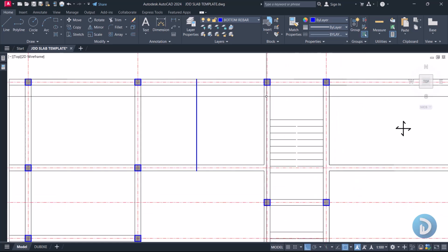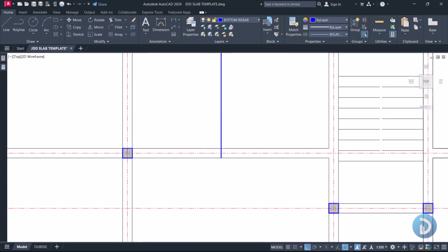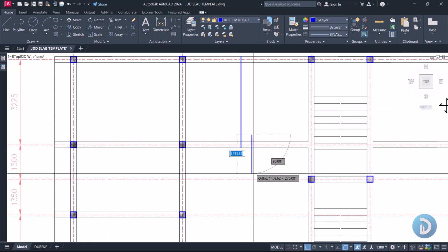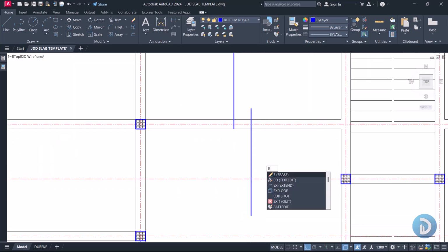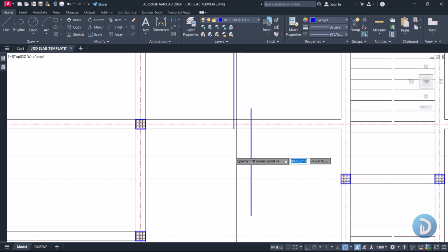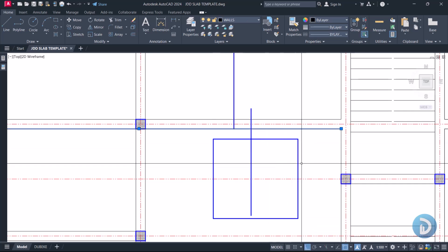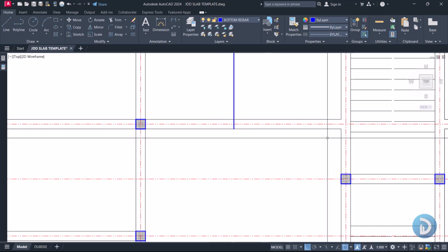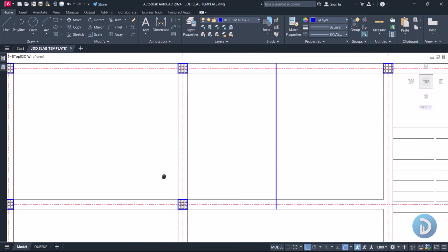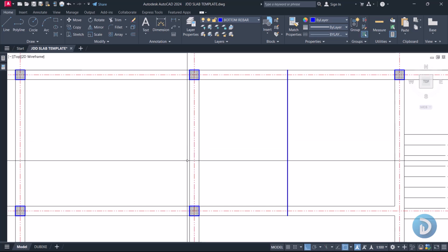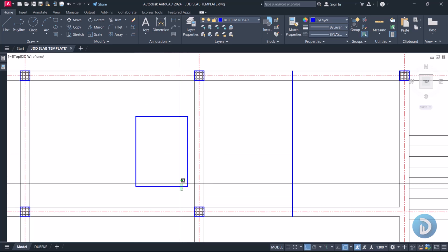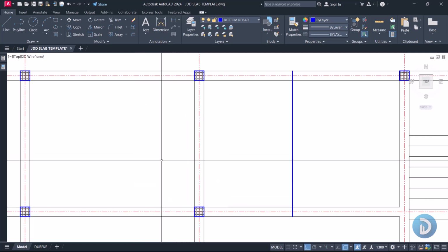All right, then if you still go in the clockwise direction, if you look at this part, you will agree with me that we have a slab just beyond this beam. Okay, we still have a slab beyond this beam. So this is a continuous edge. All right, this is actually what will be considered as a continuous edge of the slab. Same with the left hand side, we also have a beam here, but beyond this beam we have another section of our slab. So this will be considered as a continuous edge.